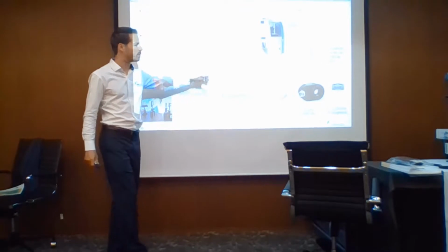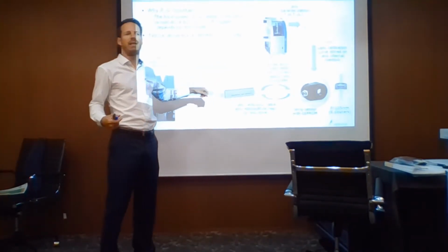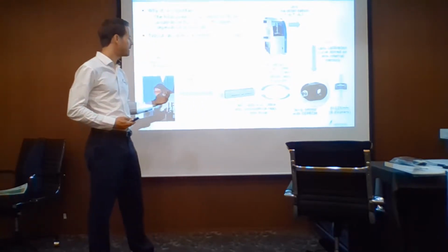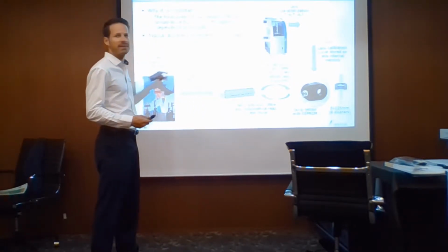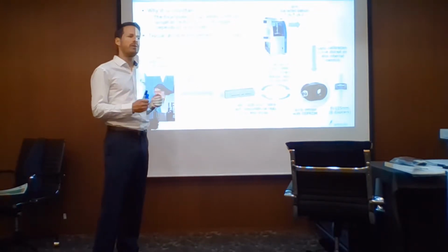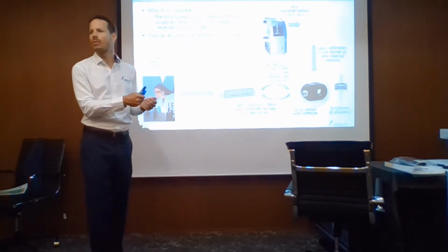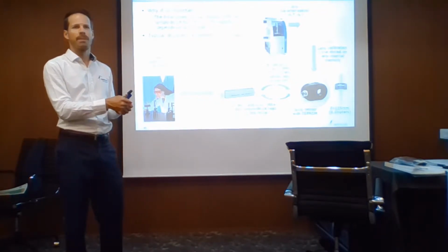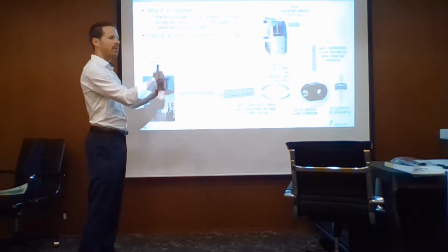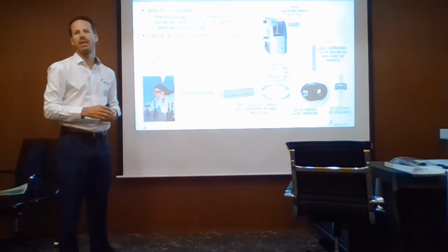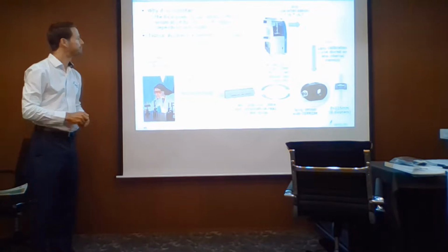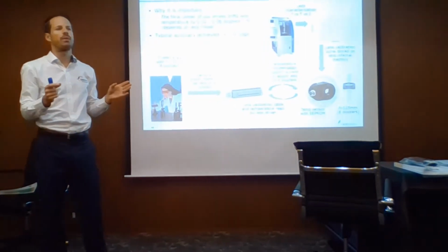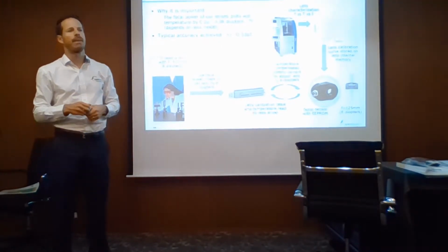The driver can read out the temperature, and at the beginning when you connect the lens, it will read out the calibration data. And then if you want to set a command, you do not set the current, because that would not be compensated. You set the optical power in diopters. And when you do that, the driver will automatically compensate the change of temperatures. Okay? Now, the typical accuracy we achieve is in the order of 0.1 diopters.